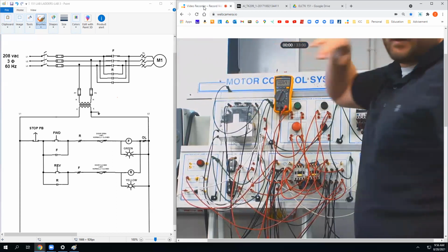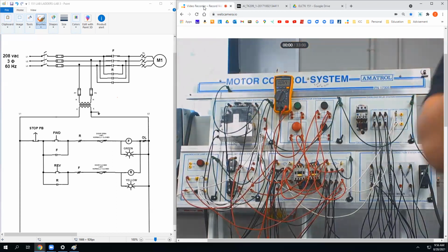Where should we start? Putting the cable you put up. I'm doing what you did. Undoing what I did? Oh, unfaulting it? We could do that. Could you start on the forward motor coil or which? Well, neither of them are working, right? Yeah. Would it be, look at the stop button? That's open. Yeah, but that's really not an output. So you could start there, but it's kind of random, right?